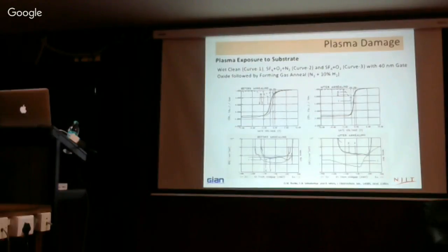Okay, and it also changes with the doping. In those devices you cannot do N plus doping. You have to moderately dope the substrate. What is your substrate? P-type silicon substrate. If this is P plus, the contact is not a problem. Normally those who want very good capacitors make a P substrate, and at the end make a P plus, then make a contact.